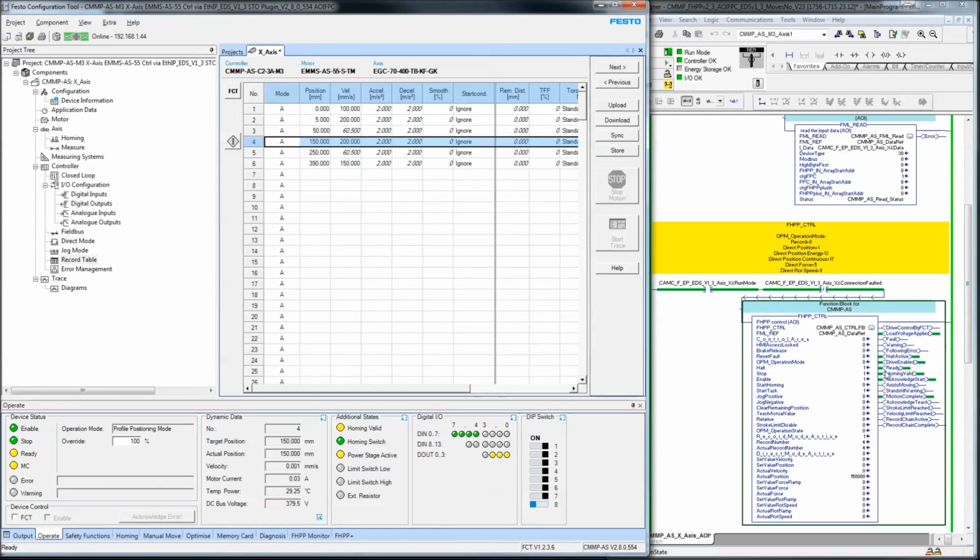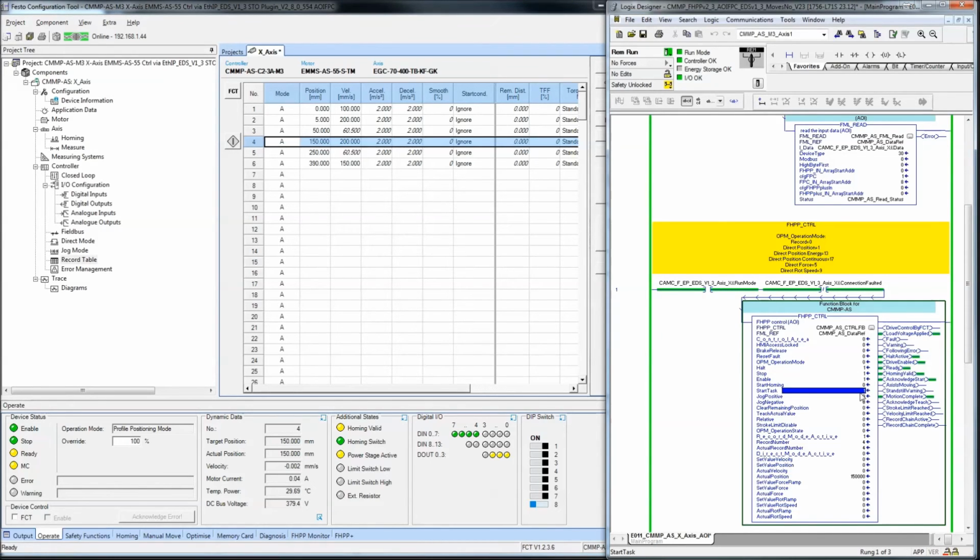When you're actually coding in the PLC, the sequence of operation is, turn on the start task. You'll see here that you have an acknowledge start right here. That's your handshake to say it's being done. At that point, you turn off your start task, and the next thing that you're going to be looking at is your motion complete. Only after you've turned on the start task and got an acknowledge do you even consider looking for motion complete. Don't use the motion complete simply going off and then coming back on, because it won't work for every move. That's the proper sequence.